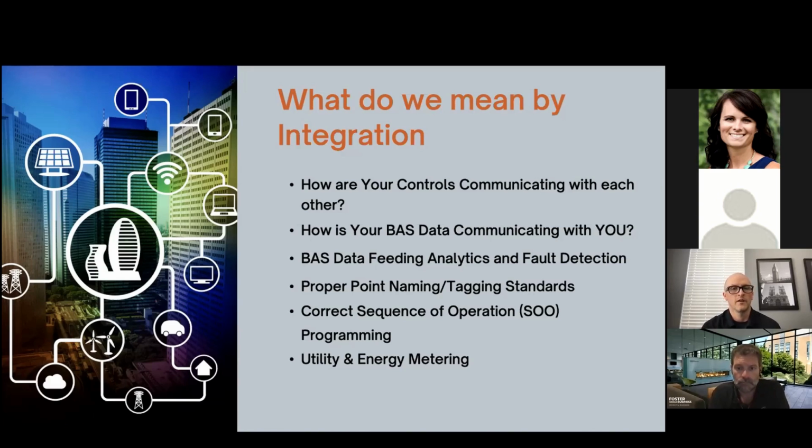And then hopefully you're going to catch that with your analytics. But at the same time, that just goes to show you how critical having a hierarchy or those relationships can be. It can really make or break the entire sequence of an air handling system with 50, 60 VAVs downstream of it. Yeah, I mean, the fault detection side of it, if you can integrate it, it will really give you a complex trend of the system, not necessarily just a trend of one point and watching one sensor, for sure.